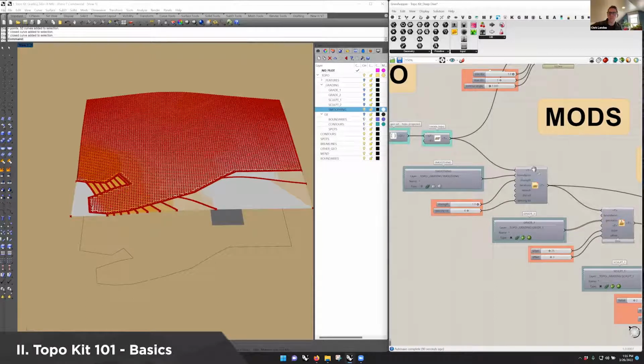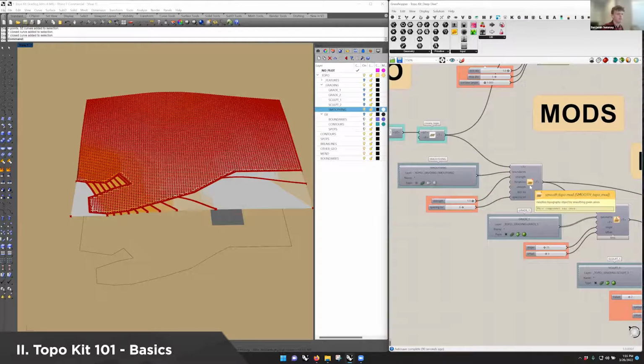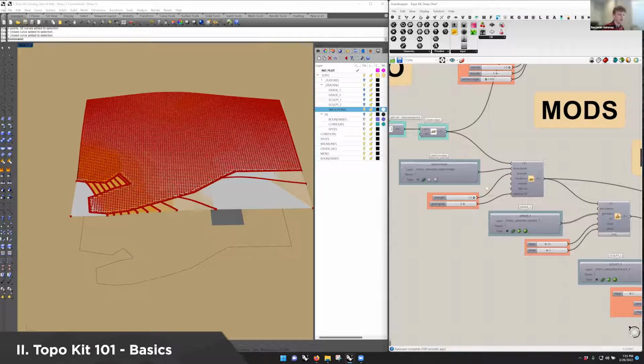These really push and pull the points on the mesh that you have, as well as the features you'll see later are creating points to manipulate the mesh. So there's a lot of different inputs here that will help you define how many points there are for the spacing along the mesh. You can make it really fine, or you can make it very broad. You could actually start with doing very broad strokes and then make it very fine once you figure it out.